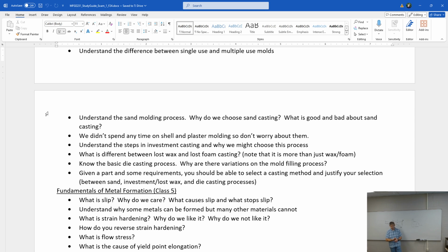Let's see, you can pour faster. You can increase the size of the runners. You can add larger risers and more vents.